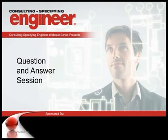Okay, thank you. Jim, Randy McInnes from Fort Mill is asking, when paralleling generators for capacity and redundancy, is it common or possible to exceed the KAIC rating of the service entrance panel? How critical is this? Is it common? Yes. I mean, is it possible? Yes. Is it common? Maybe not. But it definitely depends on what your site is.